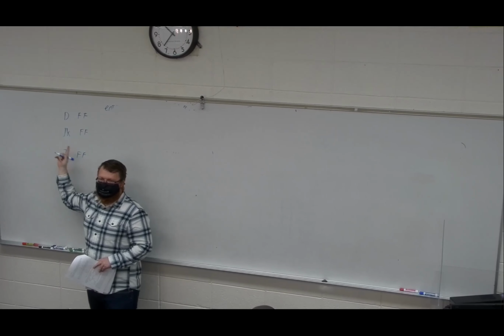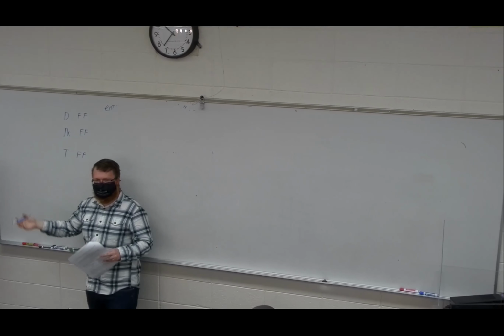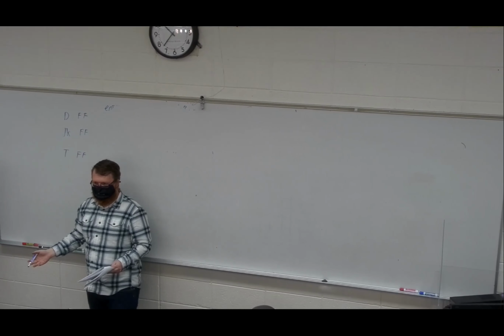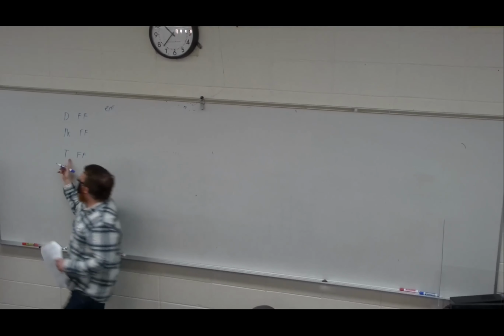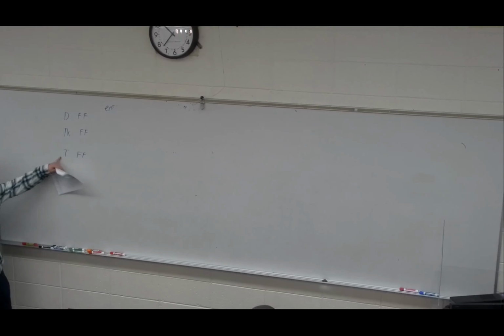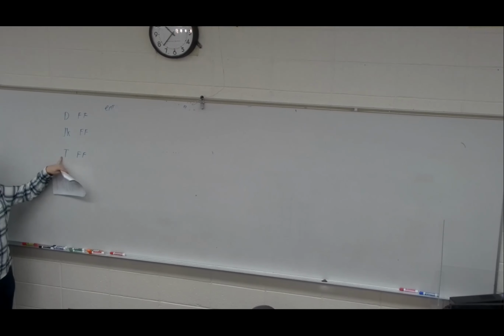It has two inputs called J and K, and it has a truth table that determines what the output is, depending on the inputs of J and K. The T flip-flop is the special case of a JK where J and K are connected together. If T is true, the output just toggles. It becomes not what it used to be. And if it's 0, it stays the same as it was.